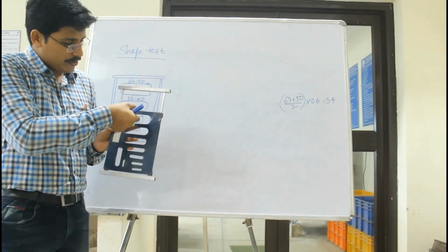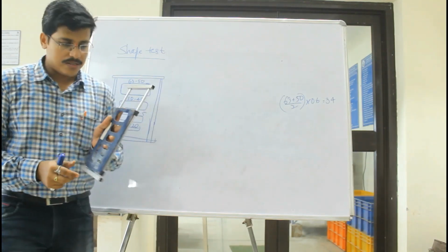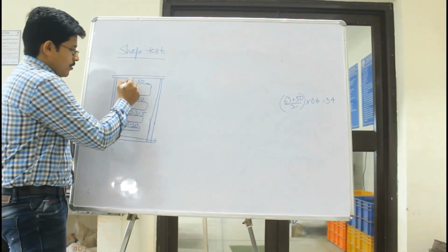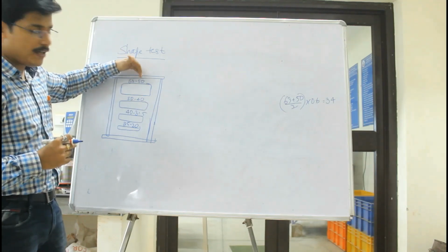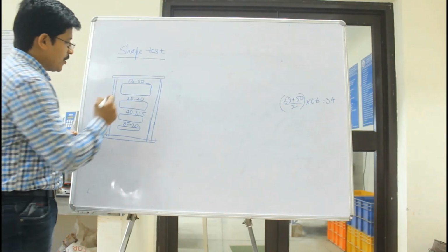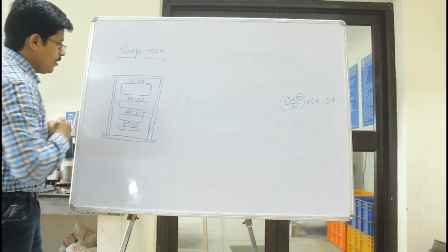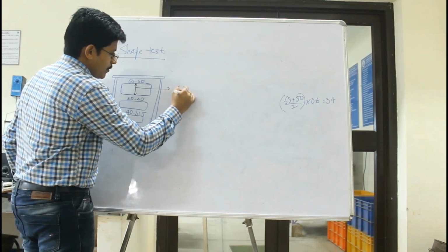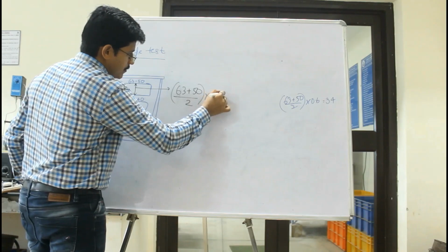Now, similarly, as I told you, there are certain openings. Now, this opening has a particular meaning. So, we will see what the opening means. So, now, we draw the figure. This particular slot is for 63 mm passing aggregate and 50 mm retained aggregate. This slot is 50 retained and 40 mm passing aggregate. So, now what is this particular dimension indicating? This dimension will be equal to 63 plus 50 divided by 2 into 0.6.